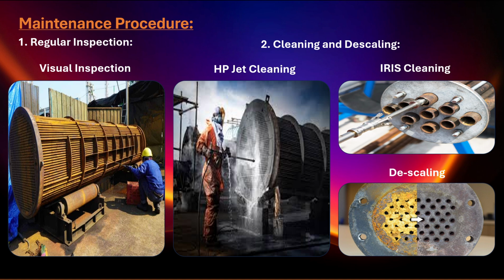Chemical cleaning using specialized cleaners can be applied with steam injection to dissolve fouling and grease without shutting down the plant completely. Cleaning procedures often involve circulating hot water and cleaning agents through the exchanger to ensure all surfaces are treated equally. Regular cleaning prevents scaling, fouling, and corrosion, which reduces the heat transfer efficiency of the heat exchanger.